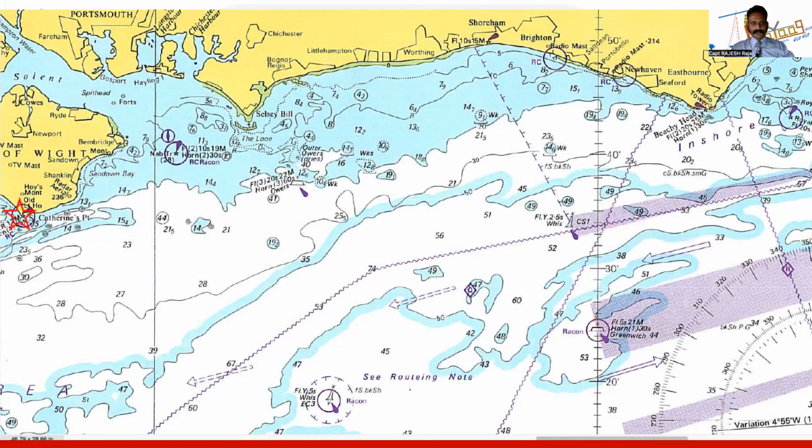So now let us take a position line and spot sounding. Let us say Catherine Point, I took a bearing and a spot sounding gave me an answer as 19.2. So here and here. So this is your fix.